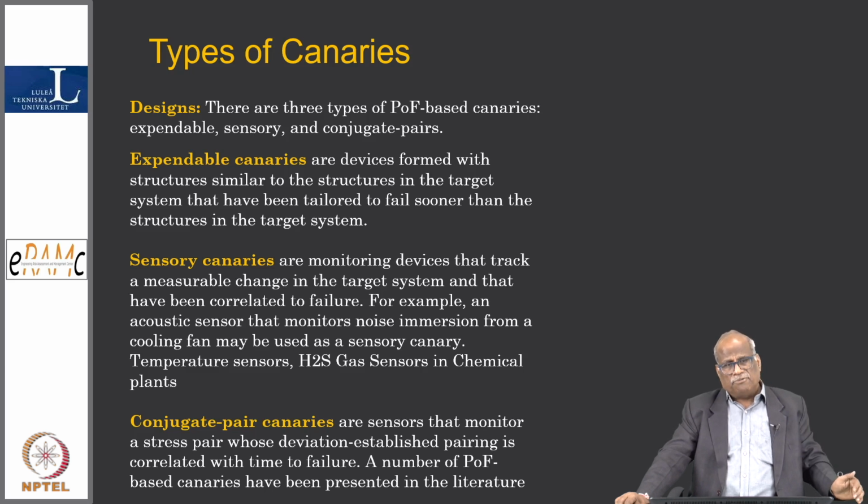So if I am feeding 5 volt, I will feed 10 volt or 8 volt for this small capacitor, which is a canary actually. So it is something called expendable canaries. You use a similar component as a canary because you want to save a critical component on the electronic board.